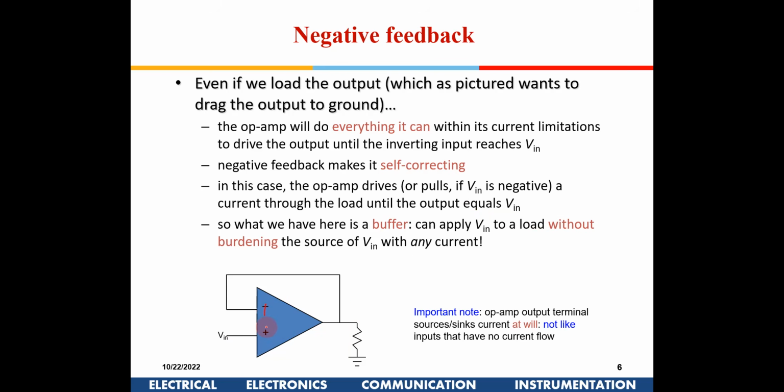Suppose this is positive and this is negative. Initially it is 0 and the input goes slightly high. So the output will go towards negative. If it is going towards negative, this voltage will go negative, which means the difference will be more. So rapidly, within no time, it will go to minus VSS. It will either give plus VDD or minus VSS, so this will act like a comparator. There is no use of that.